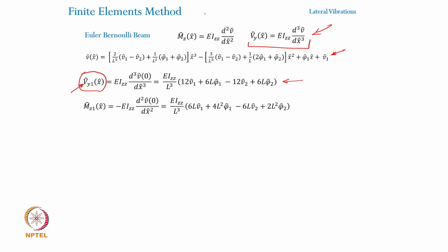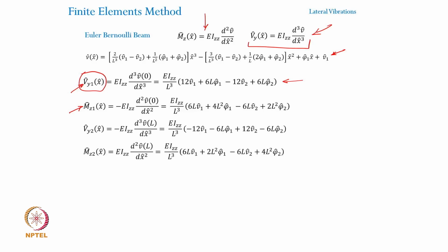On similar lines, if you use this equation, you can get the bending moment expression, and that is a very straightforward algebraic exercise which is left to you to carry out and verify whether these expressions are right or not. Same thing happens at the other extreme end. The shear force and bending moments at x cap equal to L can be obtained, and once you do that, then I can establish the relationship between the nodal forces and the nodal displacements.